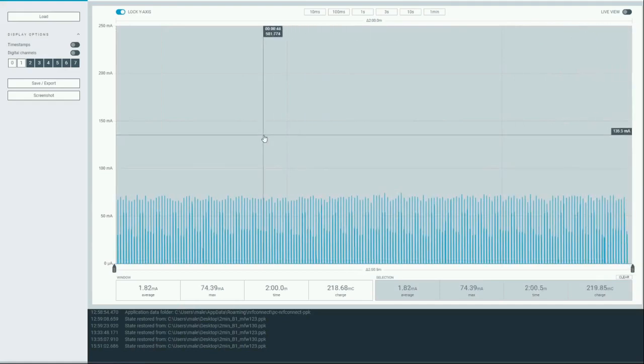So let's see the average current here. The average current in RC idle mode with the eDRX set to 0.64 seconds, which is a very high active interval, is quite a high number: 1.8 milliamperes, when using modem firmware 123.